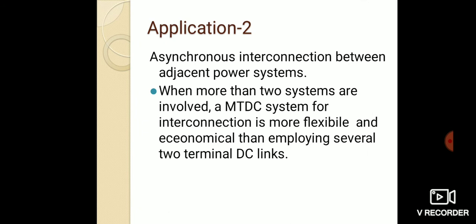Application 2: asynchronous interconnection between adjacent power systems. When more than two systems are involved, a multi-terminal DC system for interconnection is more flexible and economical than employing several two-terminal DC links.